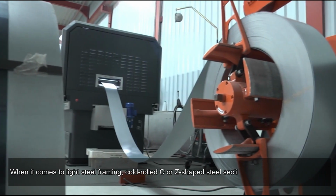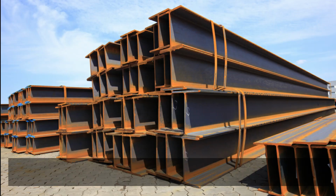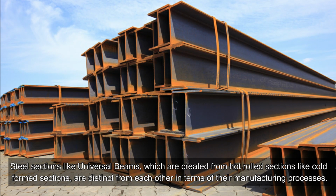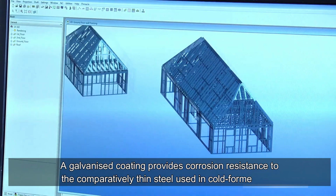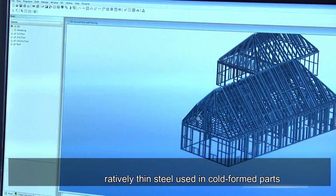When it comes to light steel framing, cold-rolled C or Z-shaped steel sections are most commonly used. Cold-formed sections are distinct from steel sections like universal beams, which are created from hot-rolled sections, in terms of their manufacturing processes. A galvanized coating provides corrosion resistance to the comparatively thin steel used in cold-formed parts.